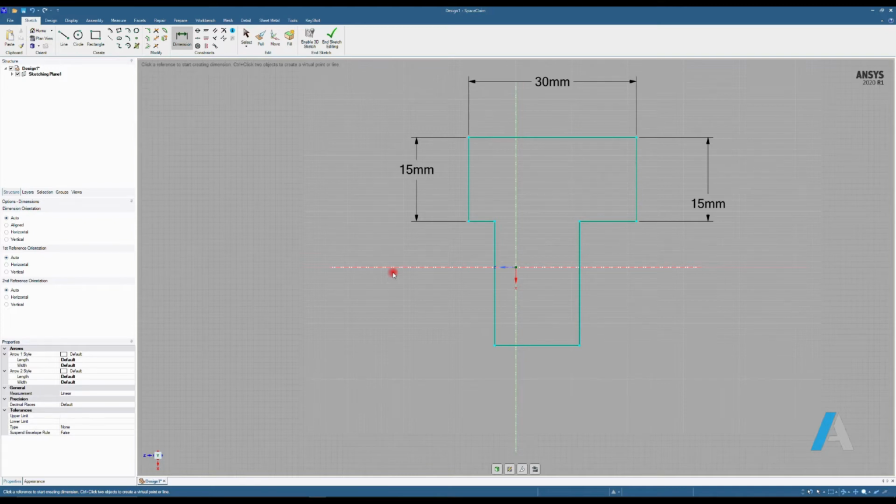That is why usually professional designers, they use constraints in their model, so once they update one of the dimensions, the rest of the dimensions will be updated automatically. For this model, I am going to simply define just a couple of dimensions.